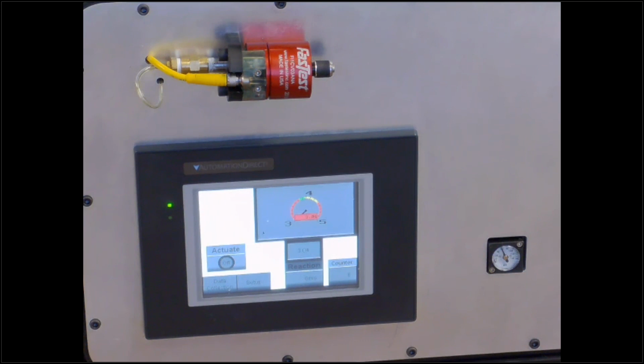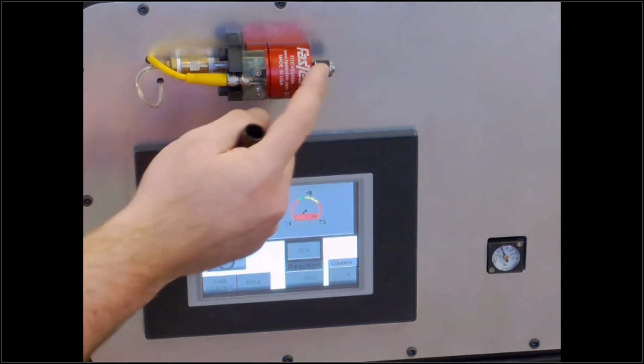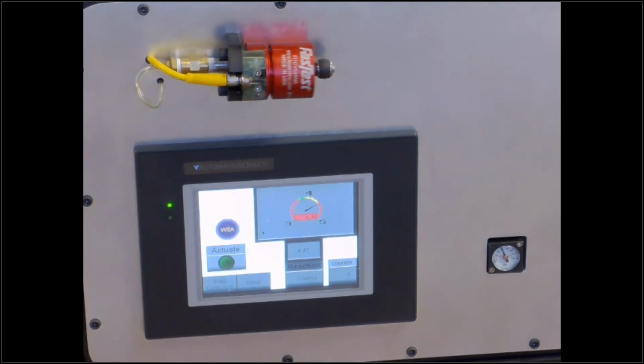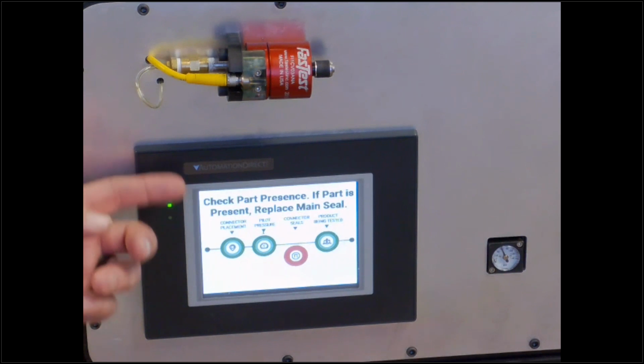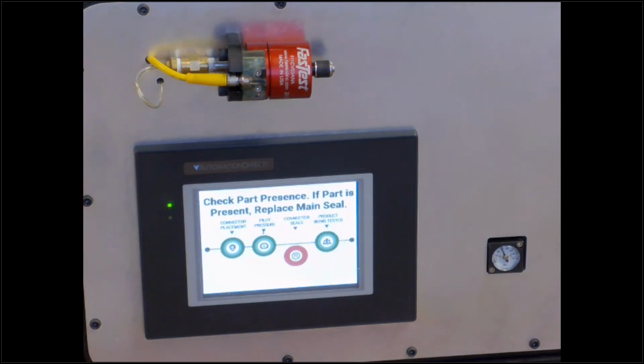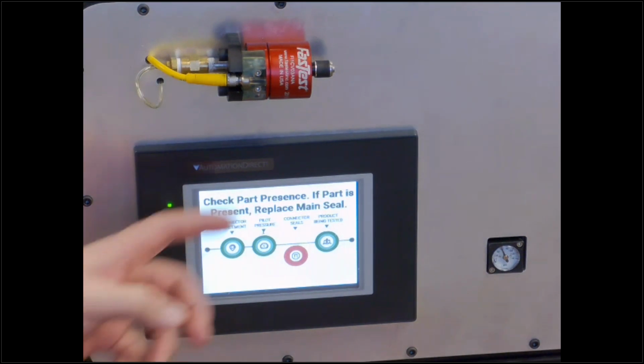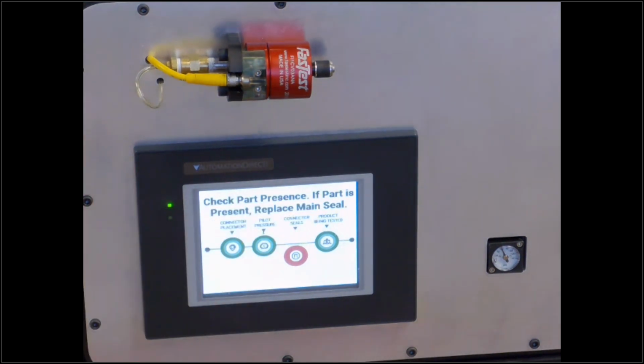So now, let's say I actuate this with nothing on there. That would mimic the piston traveling all the way forward. And I'll immediately get an error of check for part presence. This is telling the operator to check whether there is something in there. If the part is present, replace the main seal. Right now we don't have anything in there, so it's really just alerting the part presence.